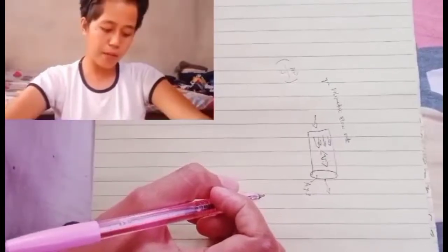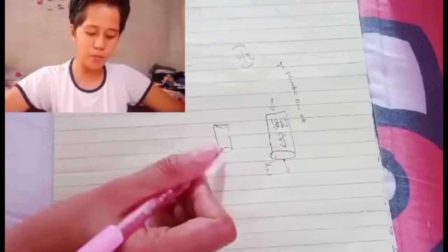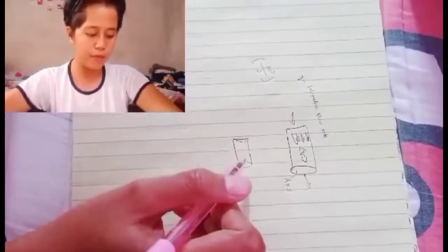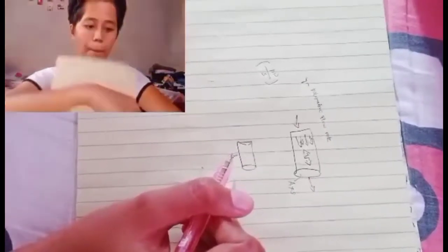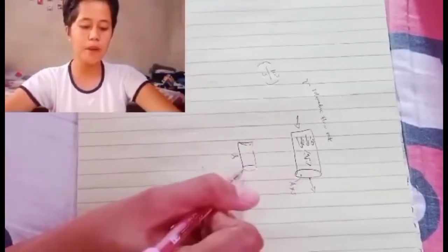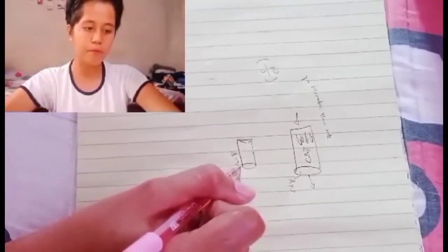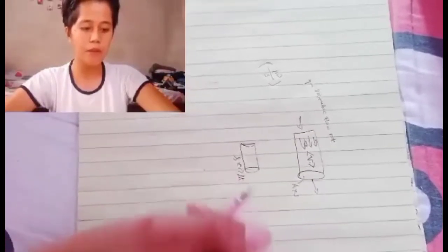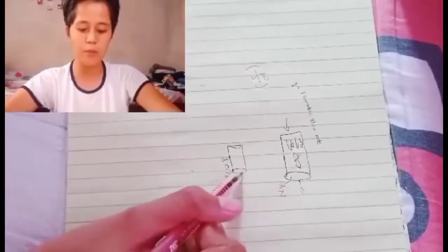So we just think about a time interval, say a time interval delta t. It has passed through some parts of the pipe, so it would look a little bit like this. There will be fluid entering and exiting over the time interval delta t. The fluid will travel a distance L, which will be average velocity times the time interval. So this is meters per second, so many seconds, that would go so many meters.